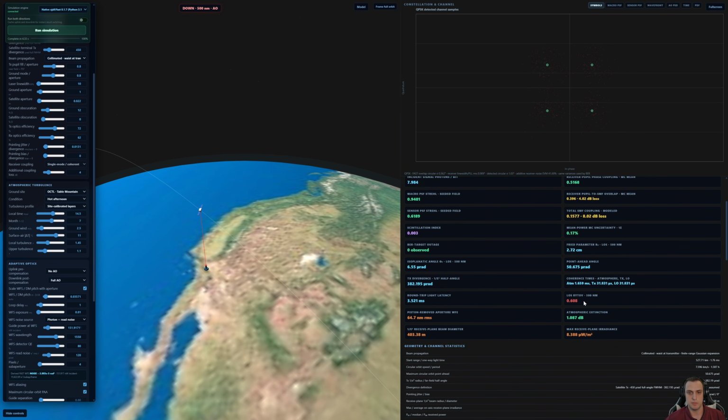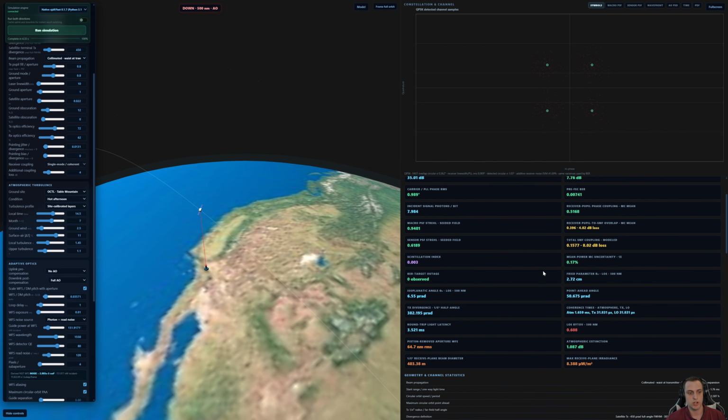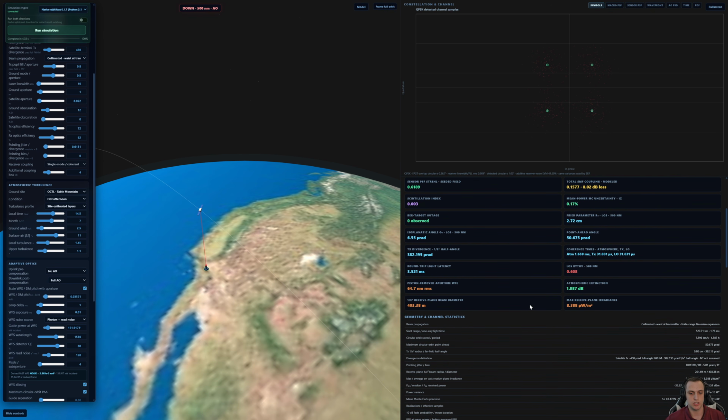One of the things I forgot to mention about the simulation is that one of these outputs is the Rytov variance. This is going to be related to the scintillation with no adaptive optics turned on. And this program, the FAST program, is mainly tested and validated for weak turbulence. And so just keep that in mind. Take the very high turbulence scenarios with a small grain of salt.